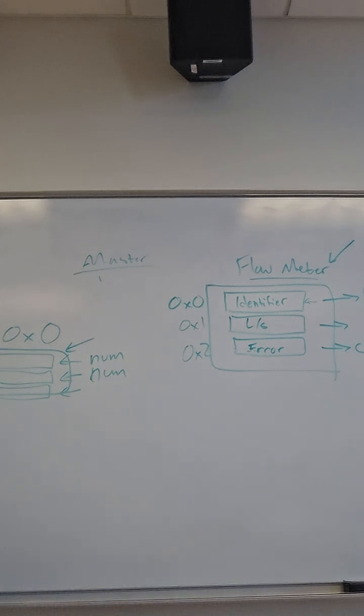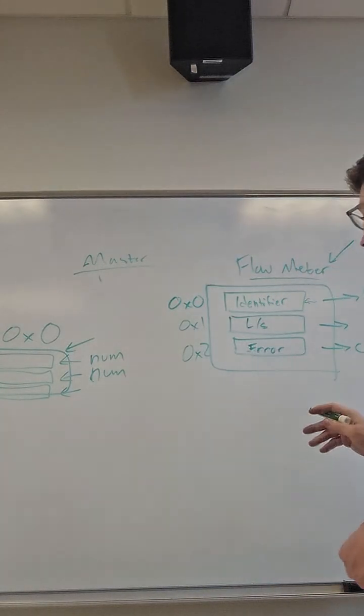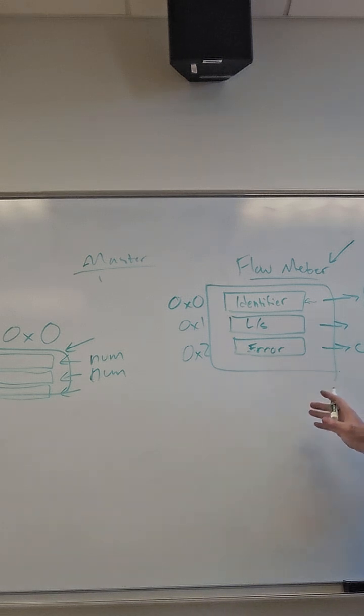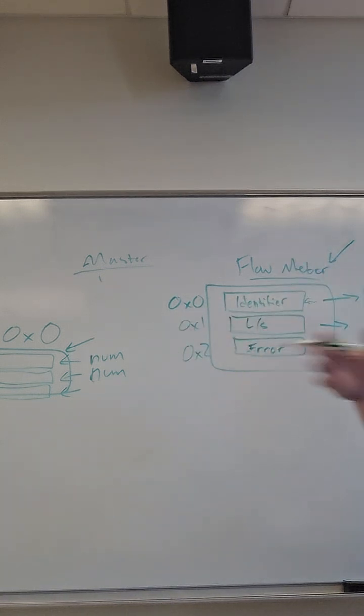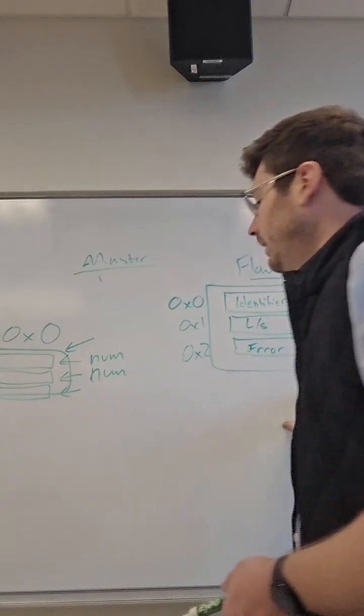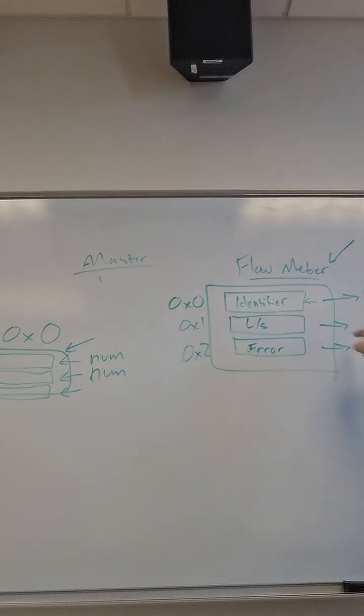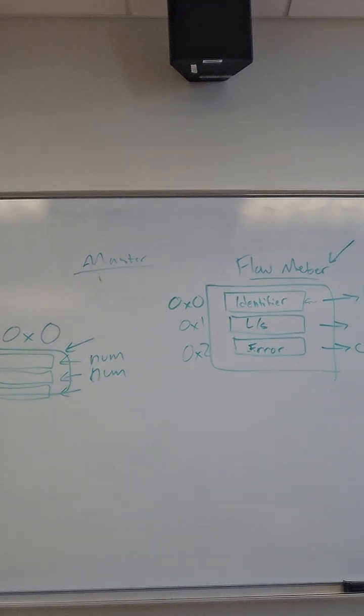So for example, if I had a robot arm that was controlled by Modbus, I might say register 4, if I write a 1 in that register, it should move to the right position, and if I write a 0, it should move to the left position. And that's one way you can control the arm, by writing a 1 or a 0 to that Modbus register accordingly. The controller on that arm would just look at that register over and over, and if it changes to a 1, it would do whatever motor movements it does. It would control the motor controller or the driver to swivel the arm to where it needs to go.